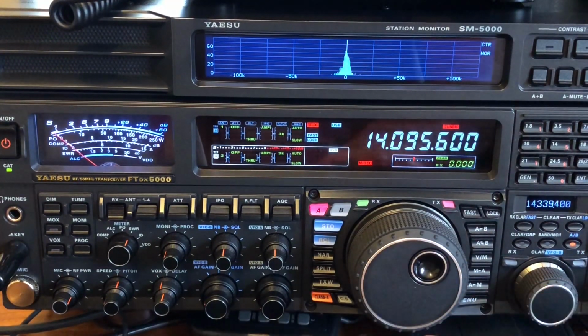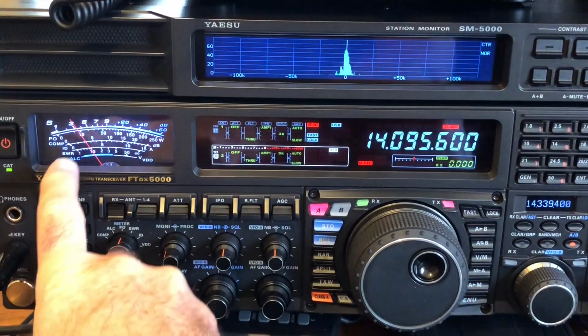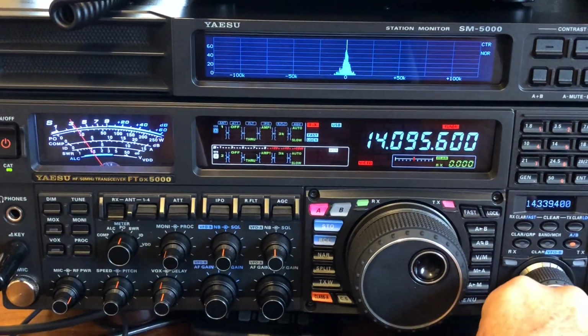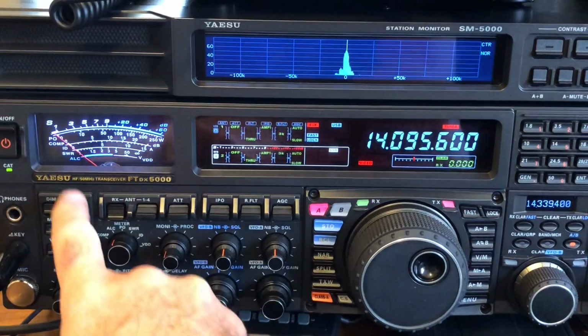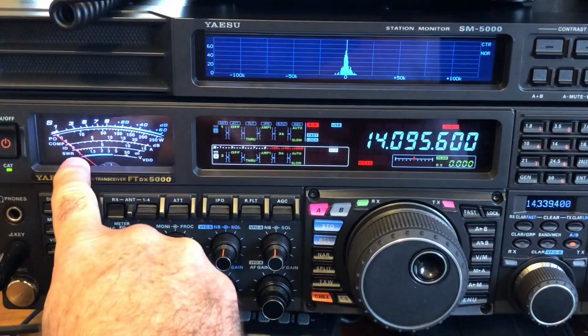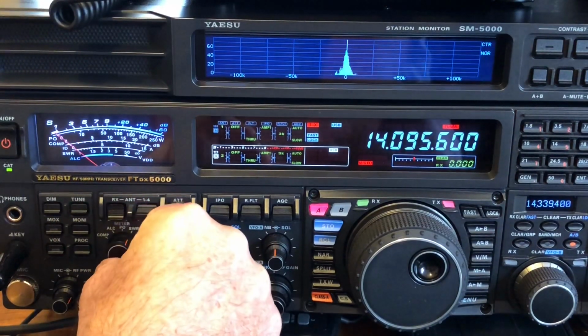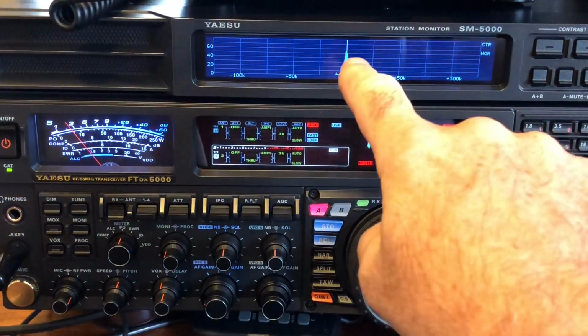So here we are, transmitting 10 watts. I had it on SWR, I wonder why it was 0. So now I can reduce that down to 5 watts. And you don't want to overdrive. The ALC is really low. You would normally on voice have it up here, but you're right down the bottom. So you can see there 5 watts. SWR is rock bottom, and you can see the signal going out.